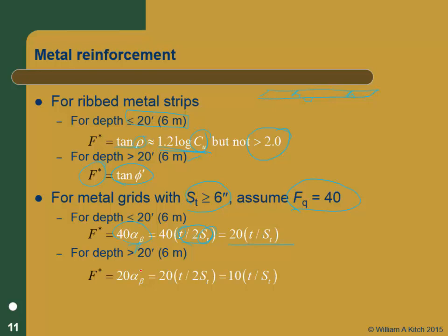Let's see if I can say that another way. If you start with a footing on the ground surface, we know as we go deeper that the confining stress at the ground surface increases the bearing capacity because it's pushing down on this failure surface. Well, if you have a pile that's really deep, that failure surface actually wraps itself back around the pile. Once you start generating this failure surface around the pile, it doesn't matter how deep you are in the soil, you're not going to get any more tip resistance.